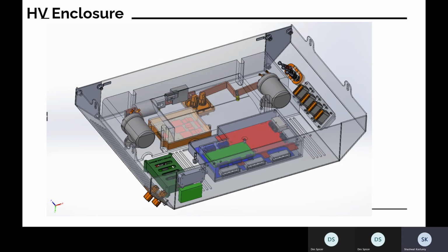We call it the AMS because it combines a thermistor sensing board as well as the BMS, the battery management system, both in one enclosure. Moving on, we have a bunch of connector banks. That's for checking voltages of the entire pack and all the signaling that has to go to the VCU and so on.